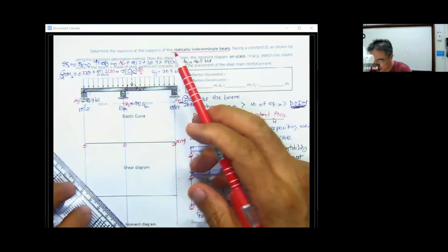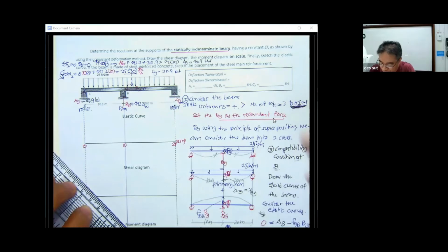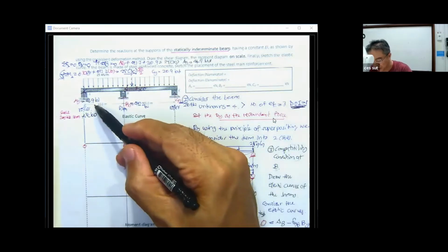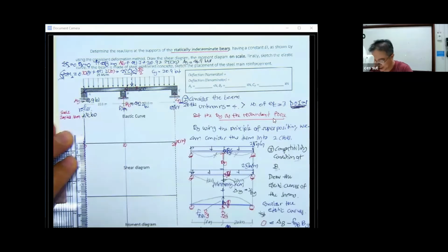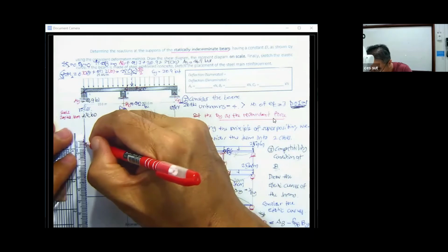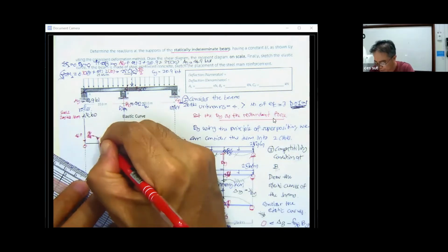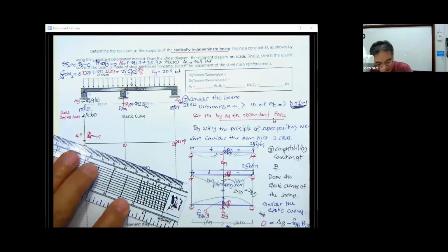It won't work. Okay, just make the scale 200 kilonewton per 10 millimeter, and set this one as the vertical line of V in kilonewton. So this is going to be very small, right? Yeah. This is going to take about 2 millimeter something. This is going to be up like this. This is going to be 46.9. Okay, and then we have dV by dx equal to minus 25. I believe it's going to be downward like this.